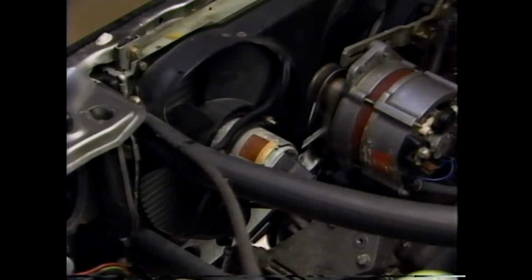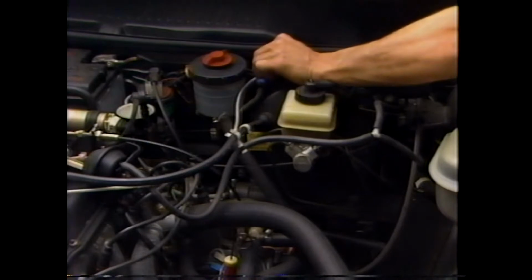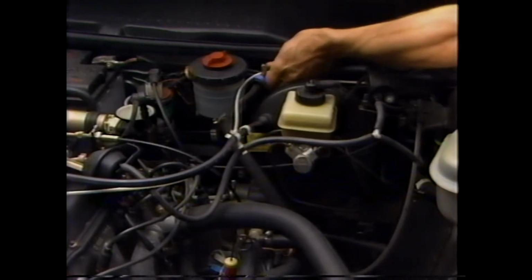If the blowout plug has opened, check the operation of the cooling fan to make sure it's engaging at the appropriate signal. If the fan doesn't cool the condenser, excessively high pressure can build up on the high side. Split, leaking, or disconnected vacuum hoses or a leaking vacuum tank can affect the operation of the air doors. This may affect cooling performance, even if the rest of the system is working properly.